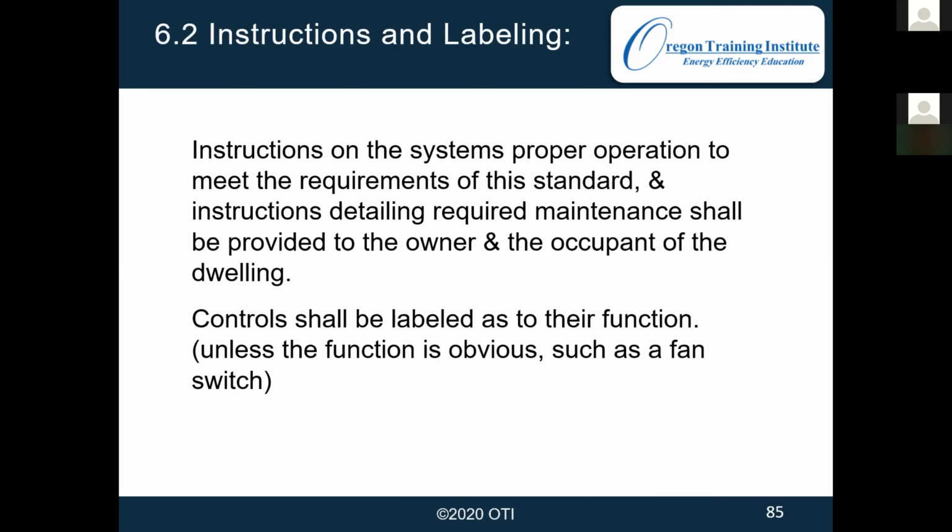Because there's going to be times the homeowner is going to need to turn it off, clean it, service it, or if the outdoor air is really bad. We had the fires in the gorge not too long ago, and the air quality outside was just terrible for quite a while. So that'd be a good time to kick off your ASHRAE fan temporarily because of the fires outside, but normally it's going to be on 24/7. Then we have to provide the homeowner with information on how to maintain it, clean it, and keep it running.